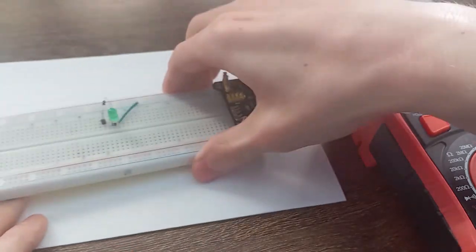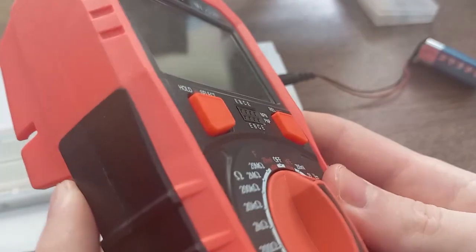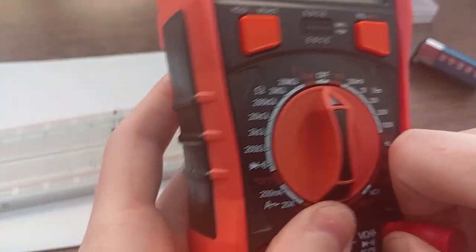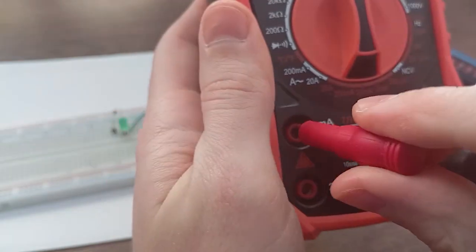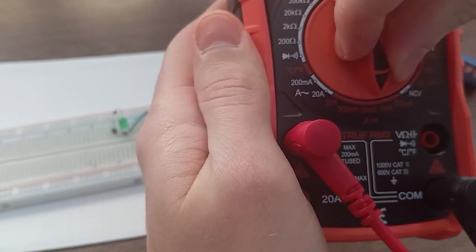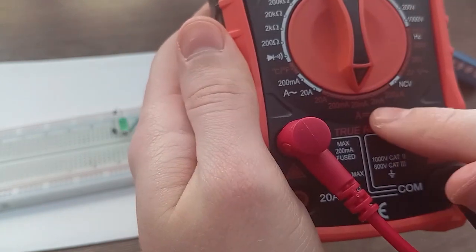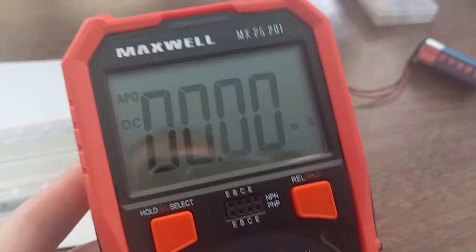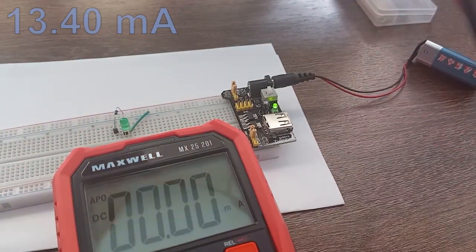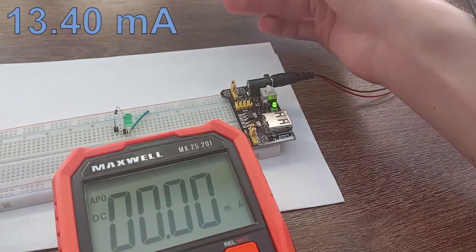But if I connect this multimeter in series, and let's see how I could place it so you can see, I will just move this to the milliamperes, set it to 20 milliamperes, and then take these probes and connect them in the proper way. 30 milliamperes. Great. So it worked.